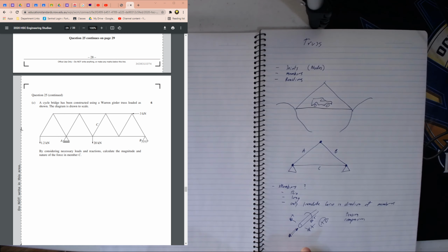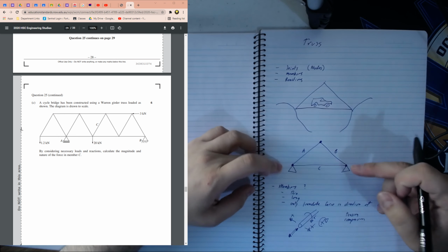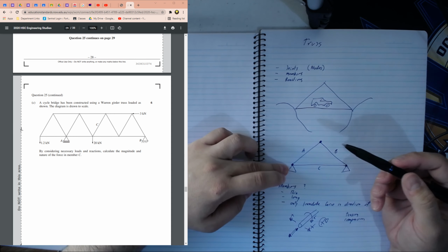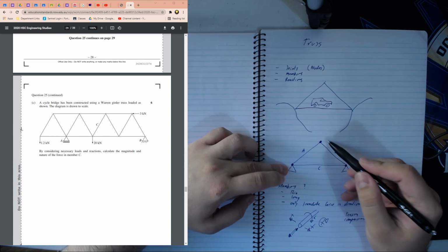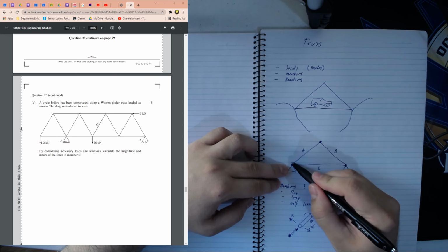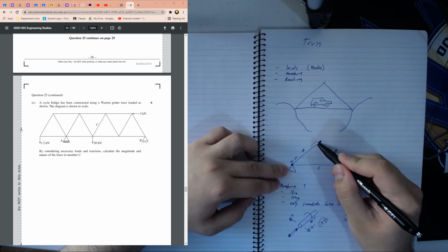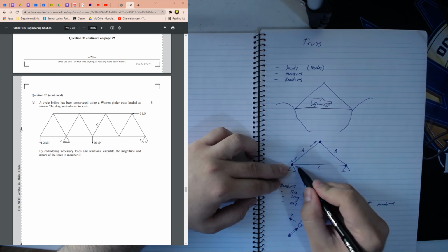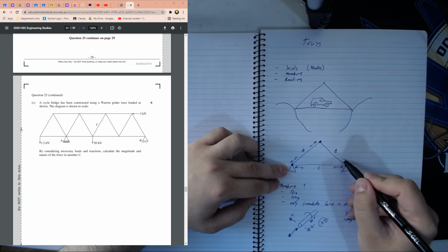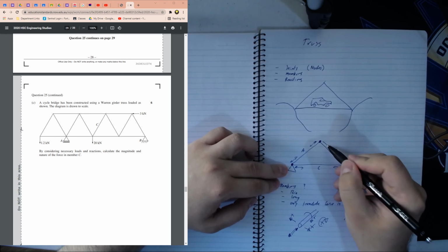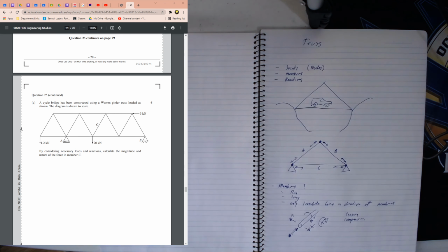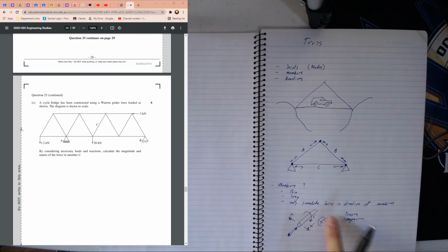This is the main thing we use to simplify our bridge. Because if we have our bridge over here, no matter what's happening with this structure, this member over here can only translate force in this direction, this bottom piece can only translate force in this direction, and this can only do force in that direction. So we can start using these simplifications to help us solve these mathematically. If we're talking about the real world, where they can translate forces in all these directions, we have too many unknowns for us to successfully solve these questions.